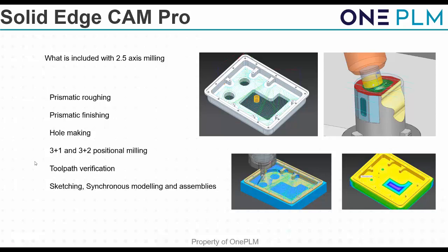Anyone that's got an old style CAM system that basically roughed out the pocket by doing what we used to call a boundary collapse method down to the center and then morphing the toolpaths out: the new style toolpaths look at volumetric material removal, so they keep the load on the tool constant throughout, so you can up the feed rates and improve the tool life. Absolutely brilliant toolpath in its own right. It really is somewhere that everyone should be going to, adaptive milling.